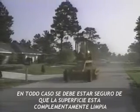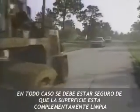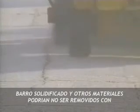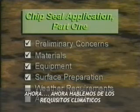In all cases, you need to be sure that the existing surface is completely clean before the chip seal is applied. Hardened mud and other foreign matter may not be removable by brooming alone. Washing or other cleaning methods may be needed. Next, let's look at weather requirements.